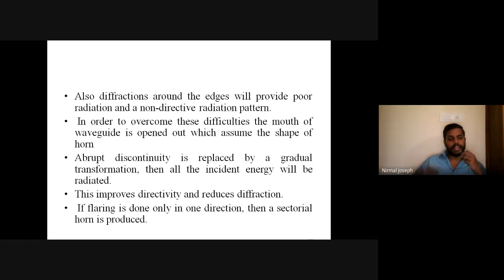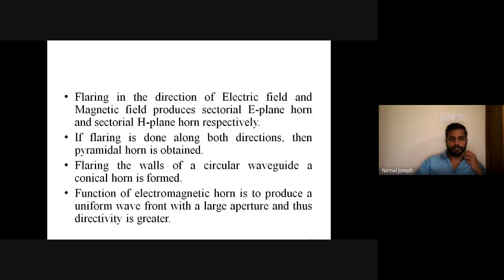So we can incorporate better directivity. If flaring is done in only one direction, then a sectorial horn is produced. Flaring means opening up. That opening up is done in only one direction. That is called a sectorial horn.